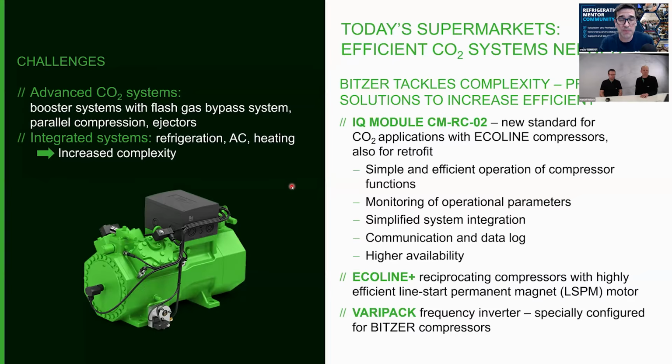Now I'm seeing more and more of that being an issue, where all of a sudden it's minus 40 or minus 30, where systems are running into more problems. And then you just said it, you got curtains pulled down, it's in the middle of the night, everything is satisfied. This is where capacity control comes in huge. But have you ever seen it with some of the manufacturers that you may have worked with where they have to add something to keep the rack running? Because even with just the Varistep running at minimum, the load is still too low. Have you ever seen that? With the Varistep, not so far, because we can really go quite low in capacity.